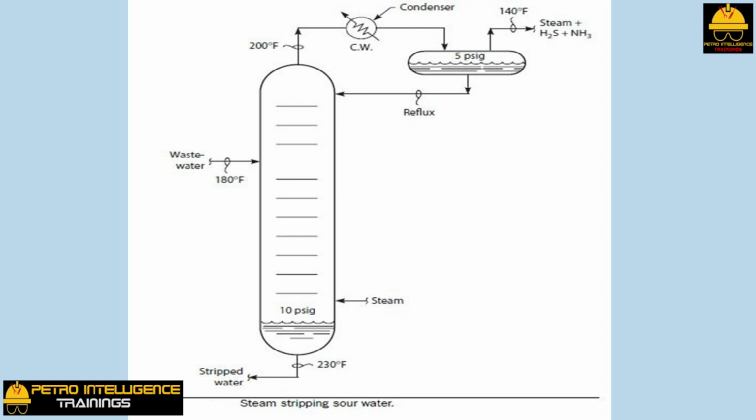The high steam content of the overhead vapors causes a water stripper to behave in a strange way. When the top reflux rate is increased, the tower top temperature goes up, not down. This odd behavior is easily understood if we note that there is no liquid product made from the reflux drum. Therefore, the only way to increase the reflux rate without losing the level in the reflux drum is to increase the steam rate to the bottom of the stripper. The extra stripping steam drives up the tower top temperature.